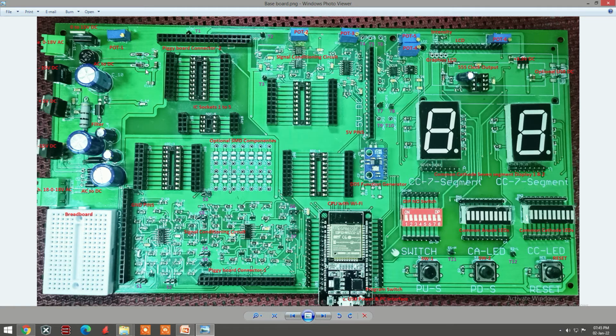So they will take care of any kind of AC ripples, which will be filtered out, and they will provide you a constant DC. Not only that, while operating the circuit, whenever switching is taking place between VCC and ground, the supply is going to be polluted. So that's why you will notice so many of these capacitors, this brown colored one, not the black one. The brown colored capacitors are mounted very close to the supply lines of the VCC because we want to maintain the constant DC. So that is one of the most important requirements whenever you design the power.